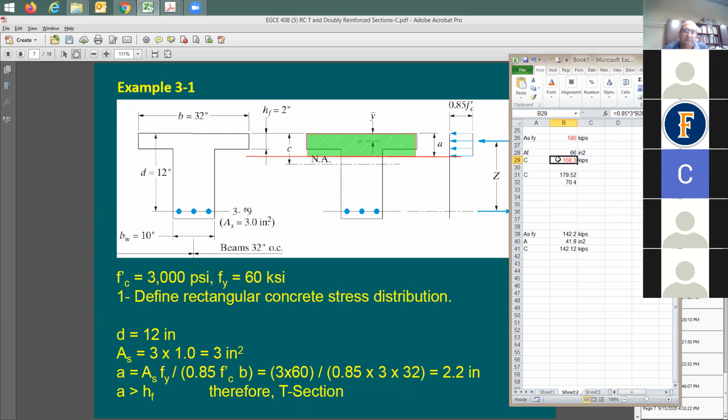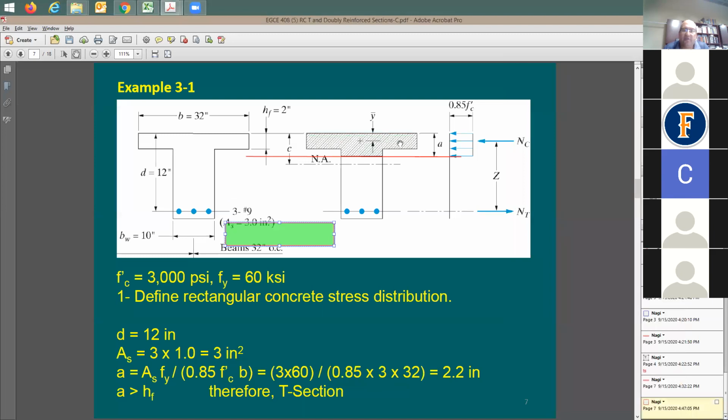We also consider that those two areas, these two little areas, are assumed to be in compression if you look at this equation, correct? When you look at this equation here, it says compression area equals 32 times 2.2, which means the whole green shaded area. But when I went back and wanted to calculate the area exposed to compression, I just used this area here, the hatched area, correct? In the given example. And this created here the discrepancy in my analysis.